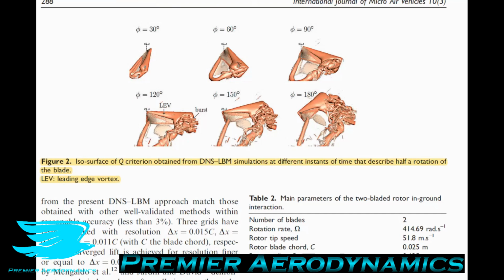The leading edge vortex develops during the initial stages of the revolving motion, but rapidly reaches a stable state, i.e., it does not shed into the wake, hence generating high aerodynamic forces. Recent studies suggest that leading edge vortex stability is promoted by rotational effects and is therefore inherent to low aspect ratios of the revolving and rotating wings. Present results further show that the conical leading edge vortex bursts into small scale structures at the wing tip, in agreement with experimental observations, highlighting the capability of the present Lattice Boltzmann approach to tackle the onset of chaotic turbulent flow.